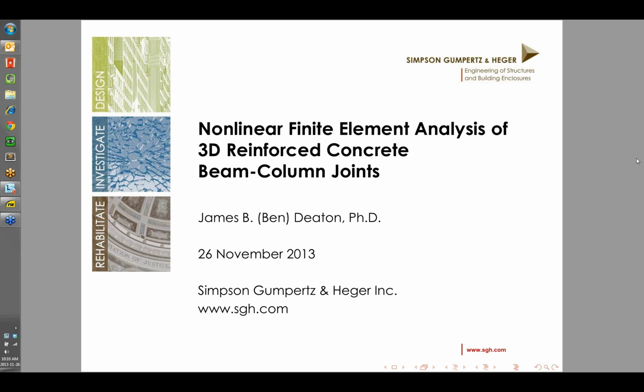And then in between the steel reinforcing bar with the plasticity model and the concrete model with the rotating crack model were interface elements that allowed a nonlinear shear stress slip relation between the two. So all the components were modeled with nonlinear behavior so that we could have cracking of the concrete, slip between the bars, as well as yielding of the reinforcements.